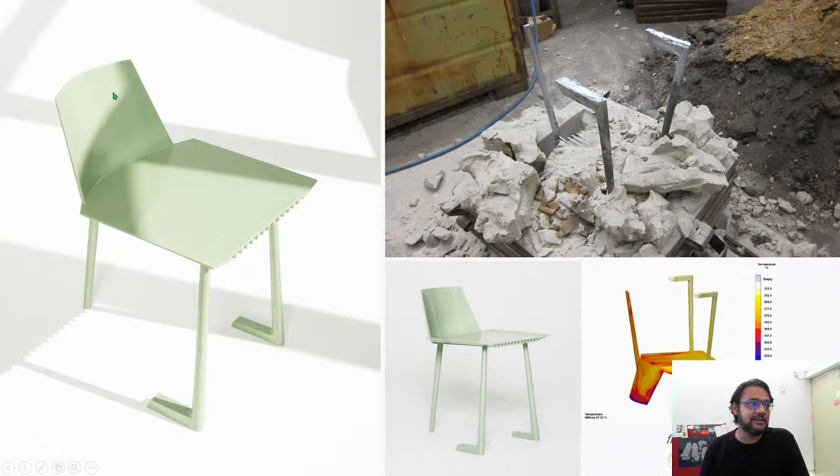So you pour in, the material goes into all of these locations which is needed for it to cast, and the rest of it comes up to these risers and fills up, showing that the material has reached all of the places. And instead of typically cutting off the sprue and the riser places, what he has done is that he has used these as the legs themselves. I thought that this was fairly ingenious, and a great idea, and it probably saved him a lot of material also. Anyway, so this is a design, and what you see at the bottom corner is, okay, let me move myself to the other side.